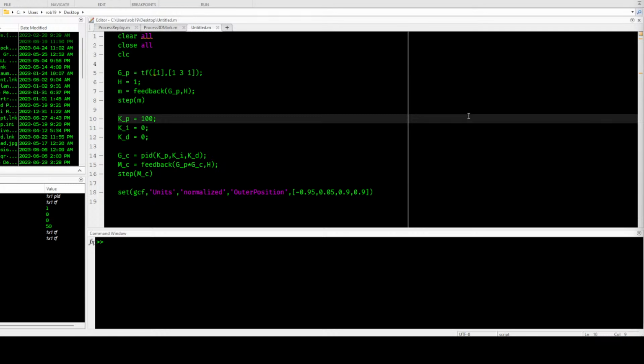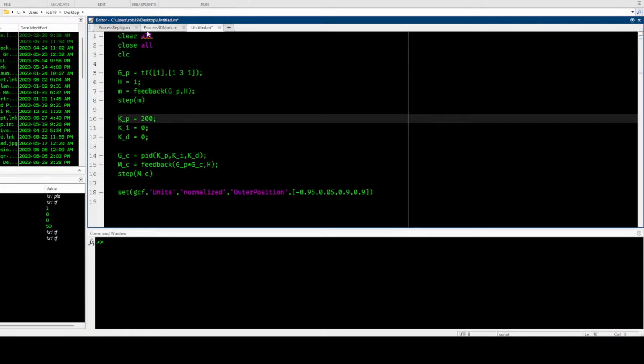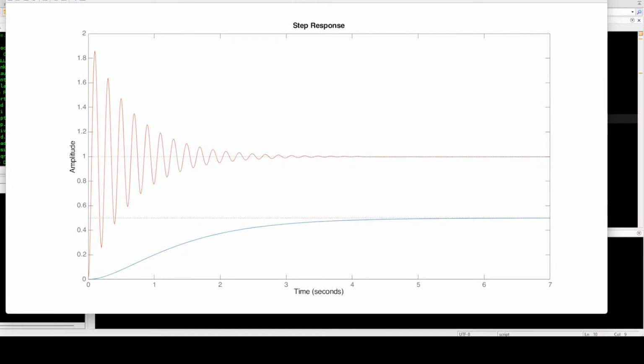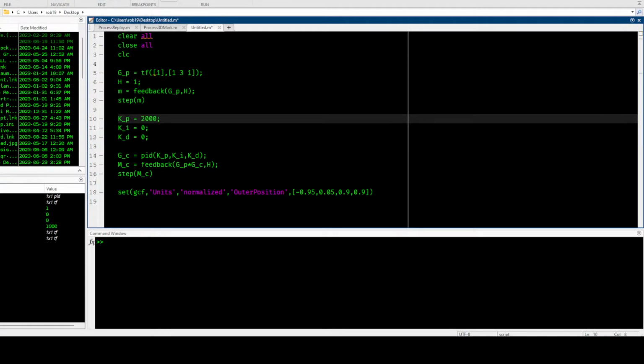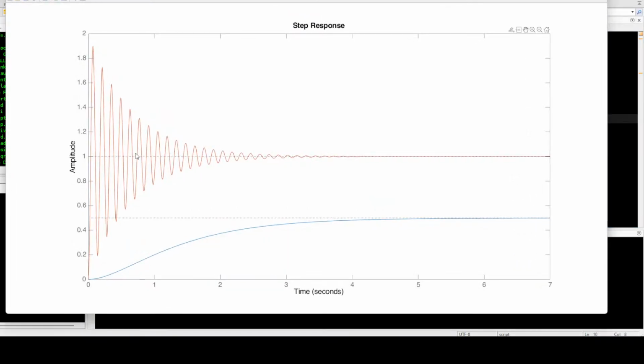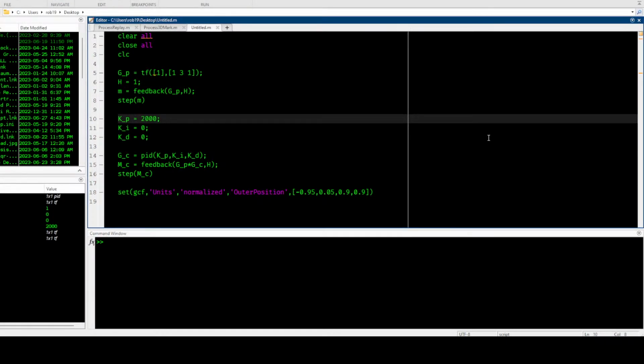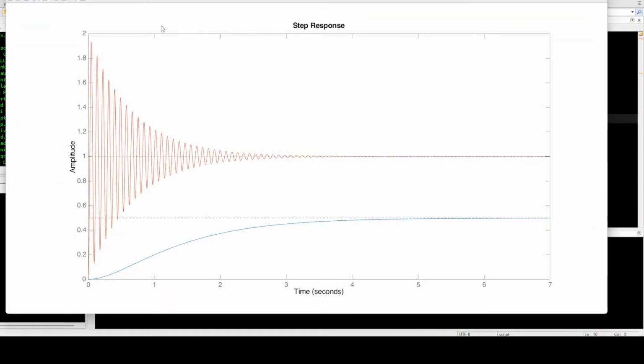Okay, so here is the basics of the Ziegler-Nichols PID tuning method. You start off with KP, and you keep cranking this up until you reach stable and consistent oscillations. The damping goes away slowly over time. You keep cranking up KP until eventually you reach a point where it just oscillates forever. Hang on. What am I doing wrong?